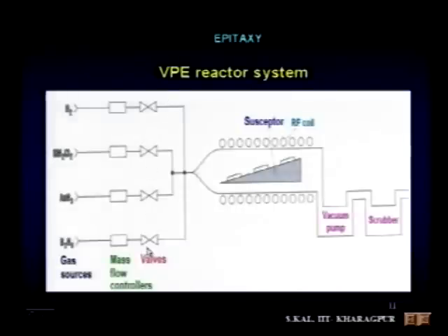And these are the valves which can close the path or open the path. And on the other side, you see the reaction will take place here. So after the reaction there are byproduct gases, and some of the unused gases will also be there. It is not true that all the silane or dichlorosilane will be reacted completely and form reaction products.